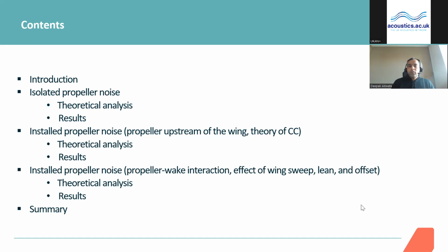After that, I will talk about the installed propeller noise, where we have installed the propeller upstream of the wing, and I will show how we can use the theory of counter-rotating propeller to predict various interaction noise sources associated with the propeller wing configuration. And I will show how there is a balance between the rotor alone and the interaction noise sources, and how